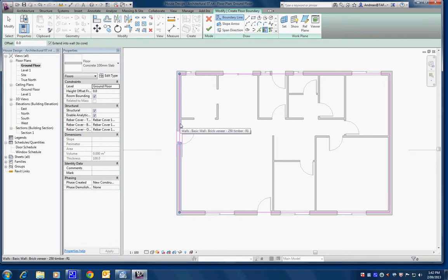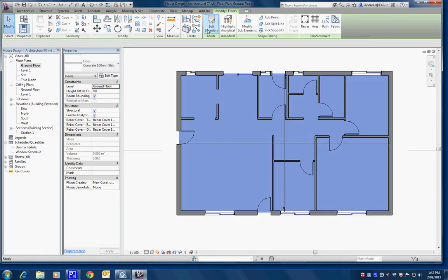So this highlights the sketch, and if that's all we want to do, we don't want to change any other properties in here, we can then press finish. And because it's a slab, it knows to put it below ground level. Because right now we're sitting on the ground floor, so anything we do will be below that now. So that's your, you might say, user coordinate system, the ground floor. That's the plane you're drawing on, basically. So there it is. Hopefully that's right.